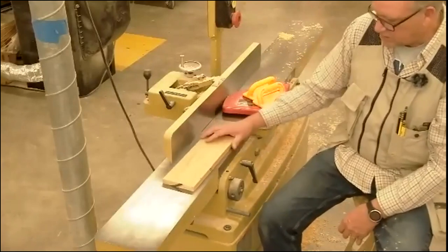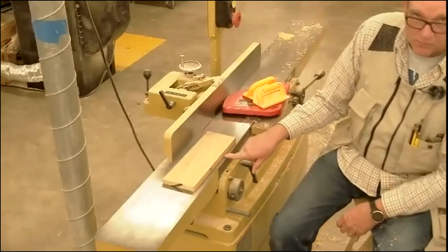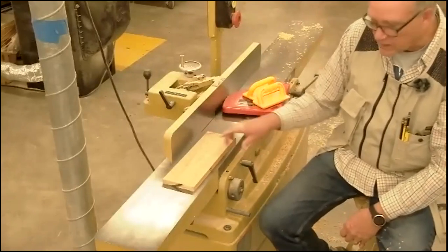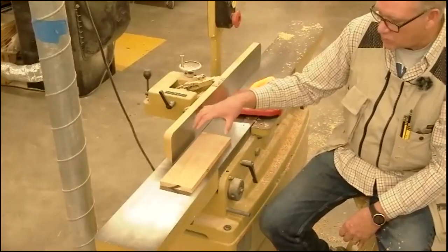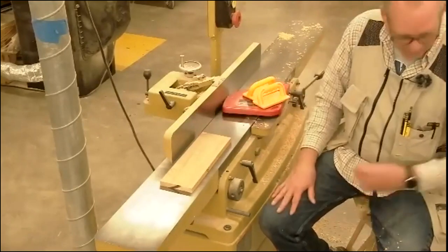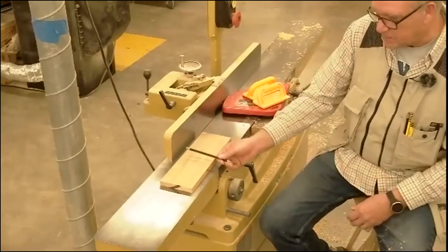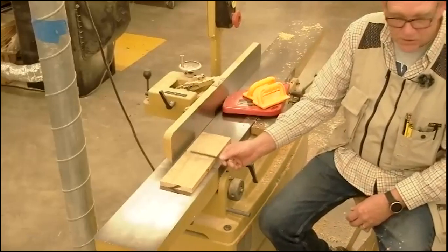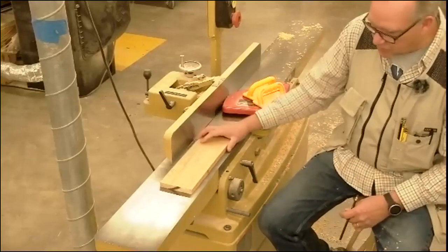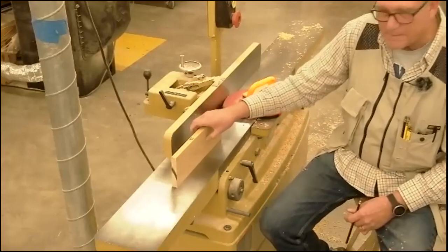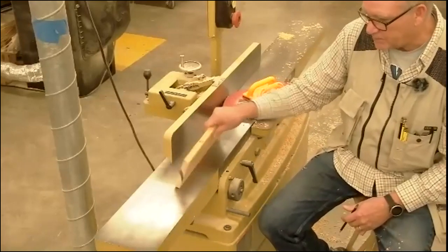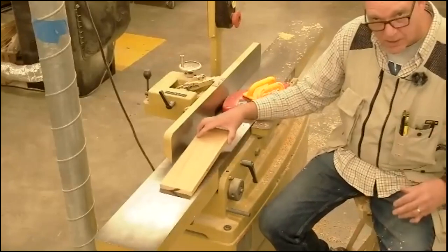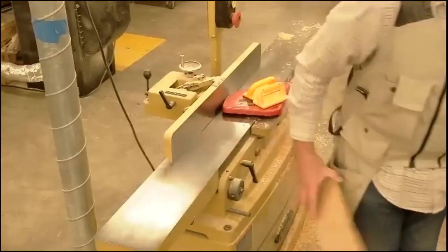Excuse me, so once this bow is taken out of one side, one face, the next step is to go to the planer. The jointed surface will go down in the planer, basically because the cutter head on the planer is above and it's going to remove material from the upper surface. So we run it through the planer, which will then create two parallel faces, and the board will be a consistent thickness. Okay, so that's a bow. A twist is a little more tricky to get out.